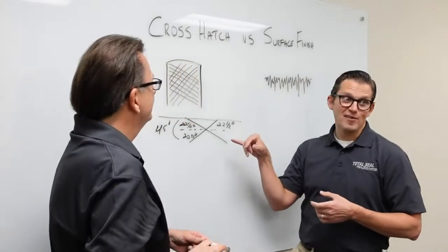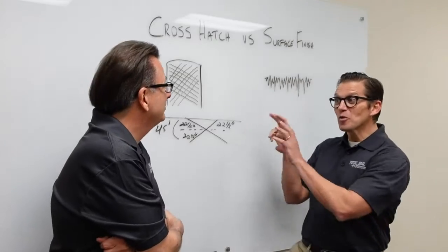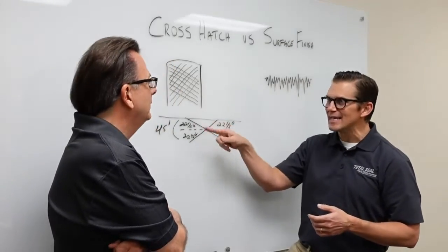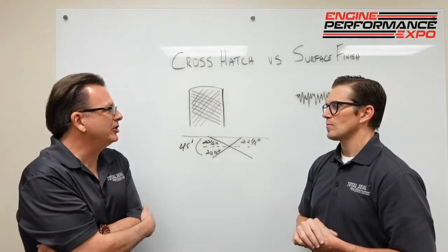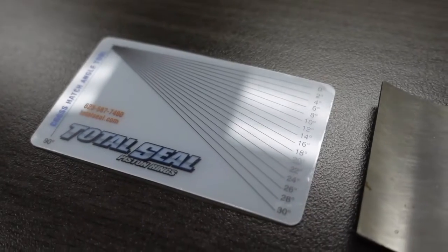So if you're 45 off the deck, you're actually 90. Yeah, so that's where it's really important to know these definitions of what you mean, included angle, and how to measure it. How you're going to take that measurement. We have some simple tools for doing that, you know, kind of a plastic protractor.